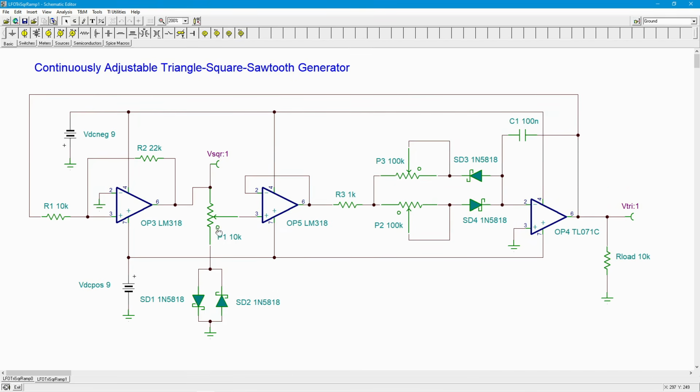Current limit. Okay, so that's not such a good idea. If you brought it up to like, let's say a 1K, which is kind of pushing it, then you'd have to increase all these things. And now you're looking at megohm or larger pots over here. And now offsets and drift and noise and whatever gets worse. So this seems to be a nice compromise for all of that.